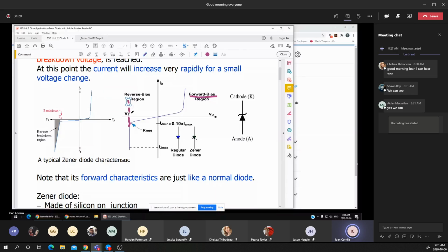If the supplied voltage is less than the VZ, the diode is in off state. You notice that if the supplied voltage is between the VZ and 0, the diode is still in reverse bias, and the current through the diode, with an input voltage less than the VZ, will be 0. Actually, it's a small current, but we are taking the approximation that the current is equal to 0 if the input voltage is less than the VZ.